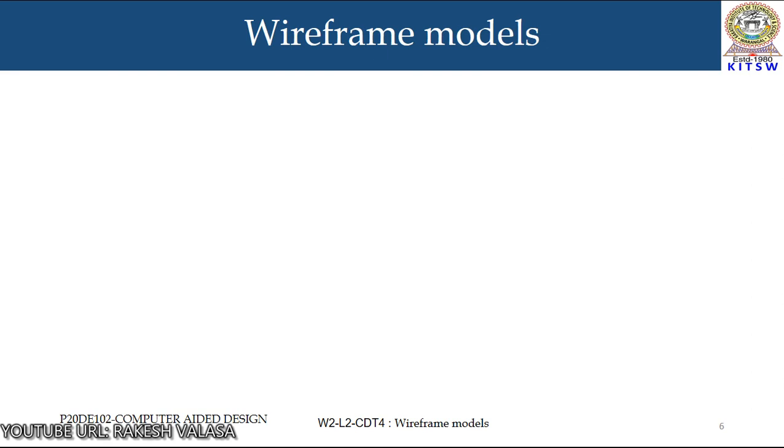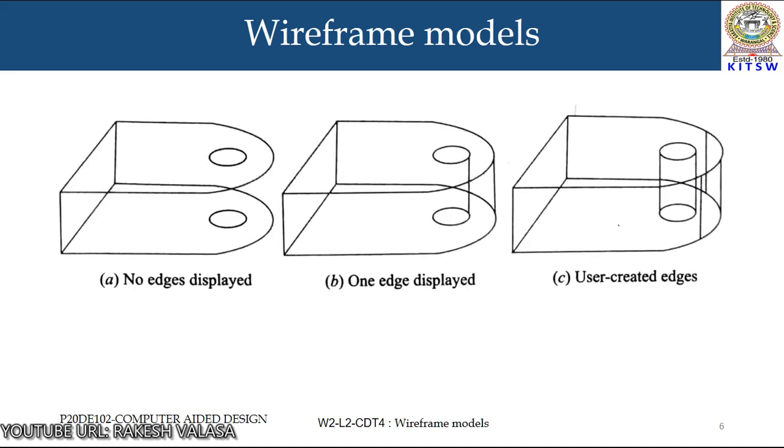A wireframe model of a box offers a typical example where the model may represent more than one object depending on which faces are assumed to exist. Models of complex design having many edges become very confusing and perhaps even impossible to interpret. To overcome this confusion, lines can be hidden, dashed or blanked. If done manually, these operations are very tedious, error prone and can result in nonsense objects.